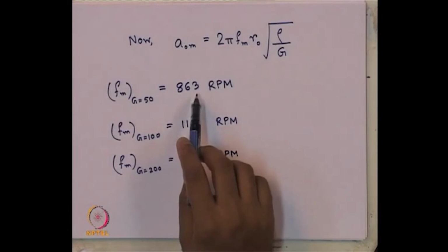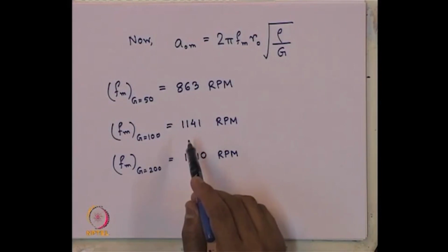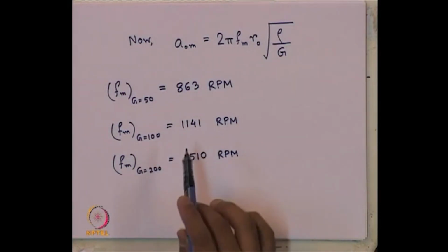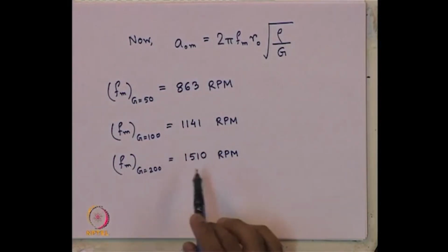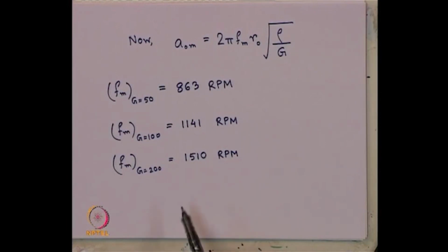Whereas, for this type of soil it is allowed, but this type of soil also it is somewhat permissible. So, remember how much factor of safety we are planning to provide, depending on that you can decide and give your judgment. So, here your judgment will come into picture, because when you are commenting on the design aspect, looking at this resonant frequency, you have to give comments on where to keep your operating frequency, in which range, and so on. So, that is why this computation of resonant frequencies also plays an important role here.